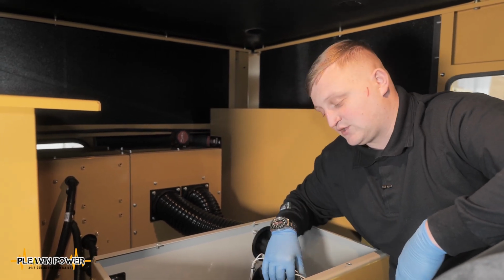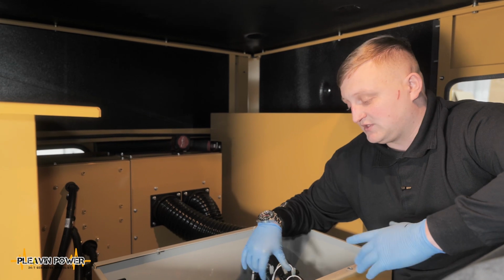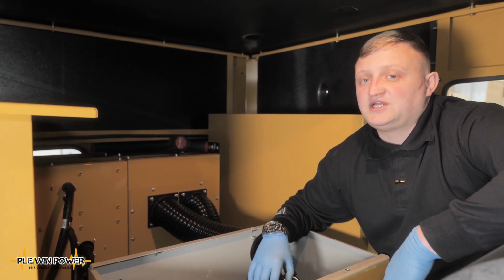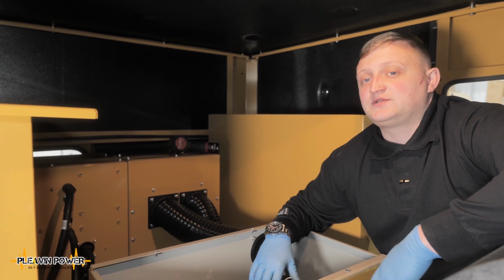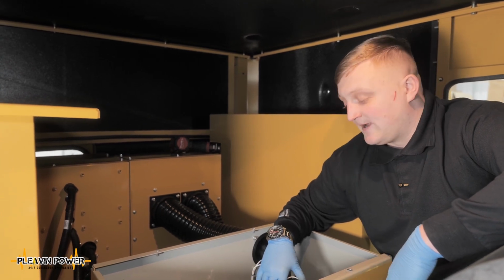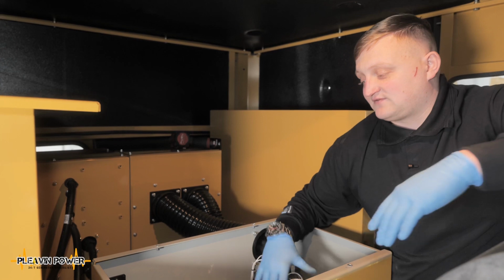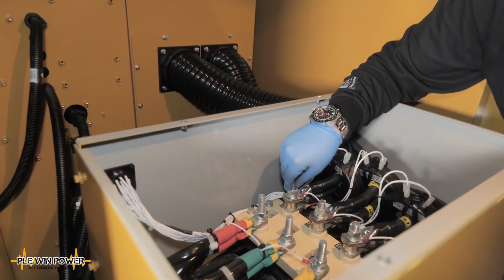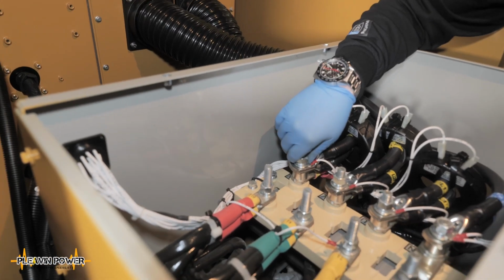If you're carrying out a routine or a 12-monthly service visit, some customers of ours like us to carry out a dielectric winding test or a PI test, which gives us an overall indication of the condition of the windings within the alternator and the insulation resistance values to ensure it's in a safe and operational condition. The other thing to check whilst you're in here, if they're fitted with anti-condensation heaters, is to make sure they're operational and there's no open circuit or damage or risk of the alternator heater failing.